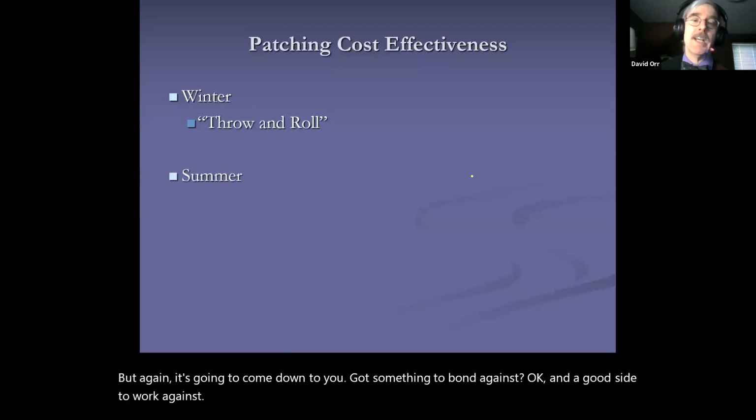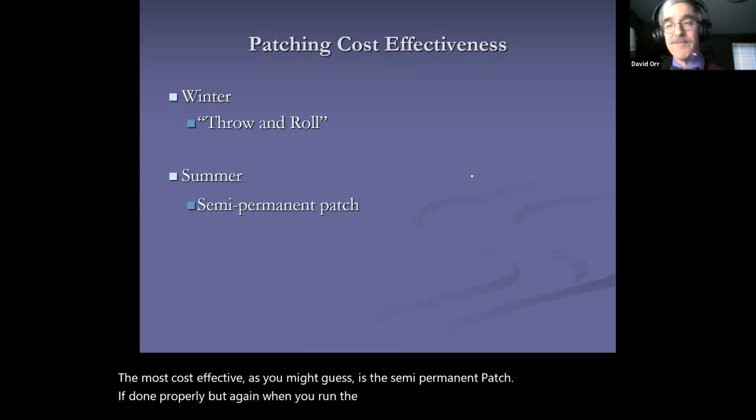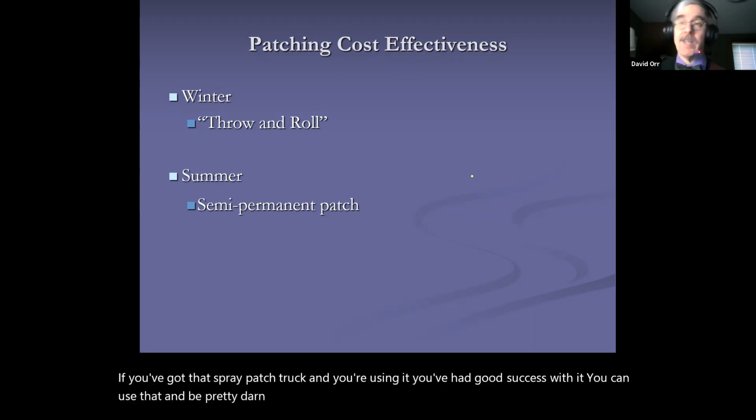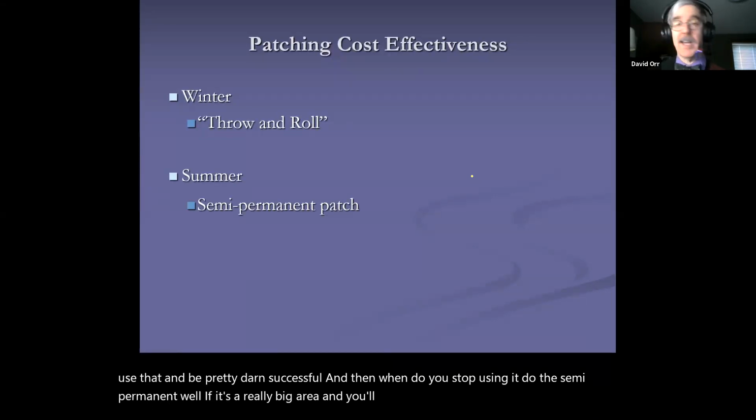In the summer, the most cost effective, as you might guess, is the semi-permanent patch, if done properly. But again, when you run the math, not by that much. If you've got that spray patch truck and you're using it, you've had good success with it, you can use that and be pretty darn successful. And then when do you stop using it and do the semi-permanent? Well, if it's a really big area, and you'll know that, you're probably pretty good at it.